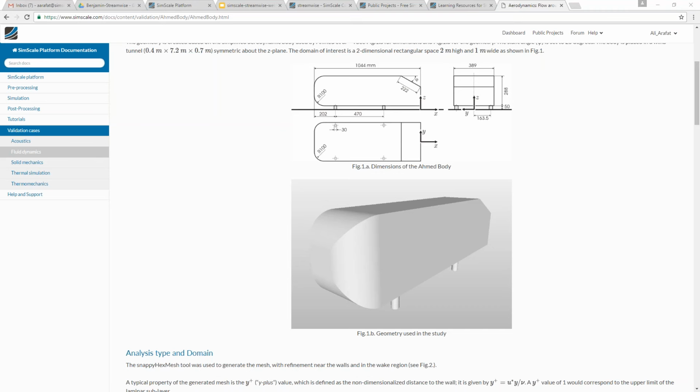Then I will continue to the next question by Gautam Das, and I guess this also relates to ProCap. The question is, is the ProCap experiment virtual? And the answer is no. It's a real experiment in the wind tunnel. You have an actual model, a real wind tunnel, real wind, and a real engineer sitting there with the probe. However, he has online data available for feedback during the measurement, such that the engineer can focus on the really interesting areas of flow around his object. As such, he can first of all focus on these areas, second, acquire data in a fast way, and third, acquire the data as a 3D data set for later comparison.